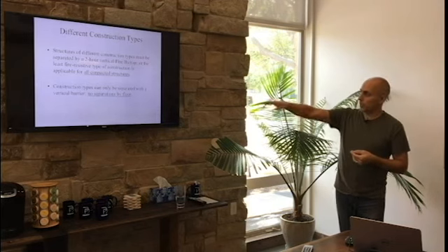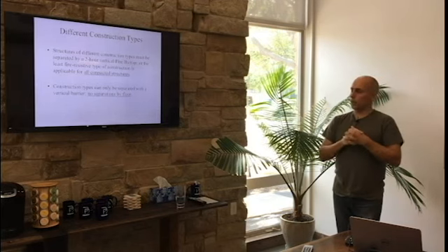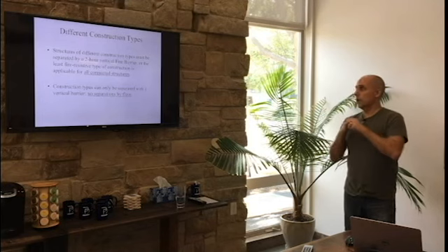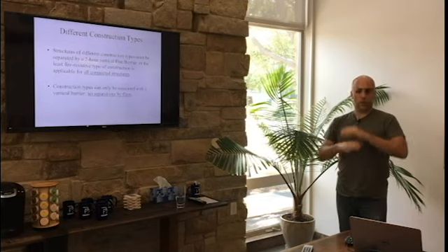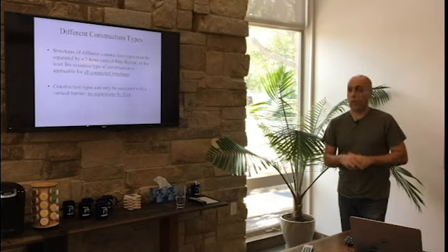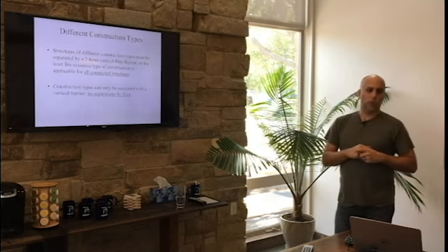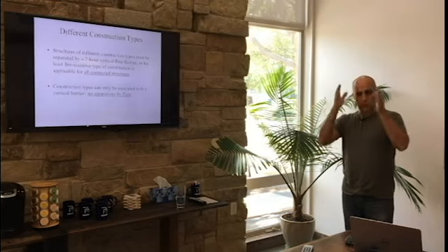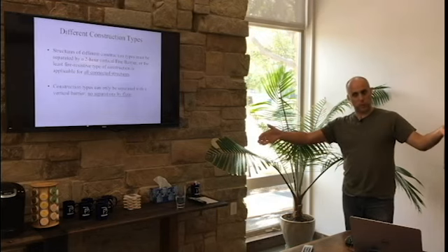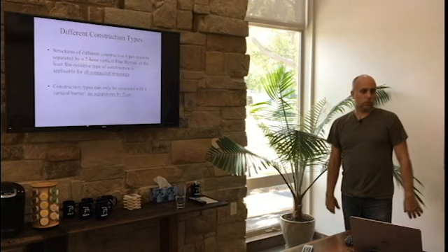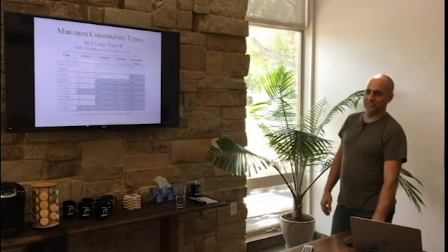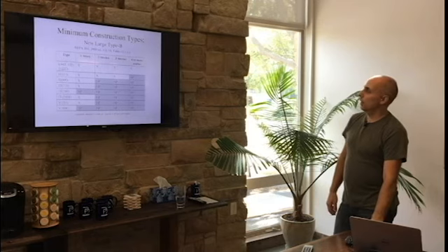And it's very clear in both the International Building Code and the Life Safety Code: it's vertical separation, never horizontal, by construction type. Occupancies can be separated by a horizontal barrier. Types of construction, or separating a building into multiple buildings because it's too big, always vertical, never horizontal. And trust me, people have asked or tried to do it.